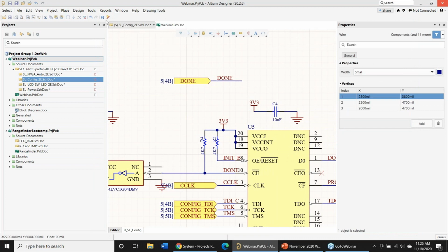Now with the improvement they've made, it used to be you had to go in here and remove all from project and then add all again to the project. They finally came up here and added update on project, which seems like it would be a small thing to add to Altium, but it's very useful now. I can just update it, and now it updates automatically. Now I normally wouldn't want the zones.